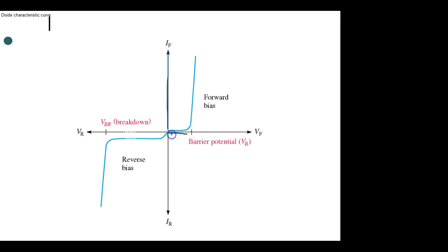Here we might have 1/10, 2/10, 3/10, 4/10. This is just leakage current coming through the diode. There's hardly anything going on, right? You understand. And then when you get up around 5, 6/10, you should start coming up, and then it's going to move in a slant, because now it's dealing with the R of the semiconductor, right?